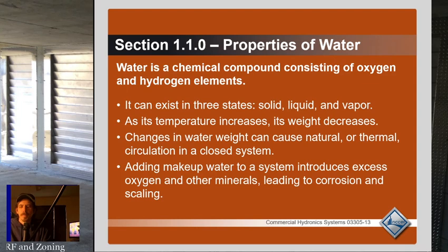One thing I recommend on boiler systems, especially if it's your own boiler system, say in your house, is to turn off your makeup water valve, right? Really, you should never have to make up water into the system. There's always going to be micro leaks and places where the water escapes, but it should be extremely slow if everything's nice and tight.